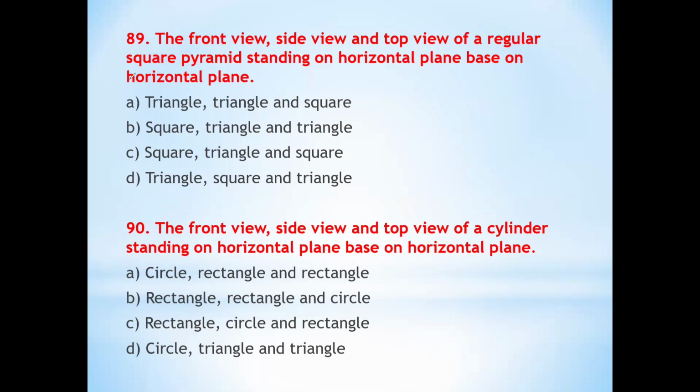So if I draw here, we'll just draw one here. Okay, so here a square pyramid is there, and it rests on HP, on its base. So with the base on HP, its top view will be a square.